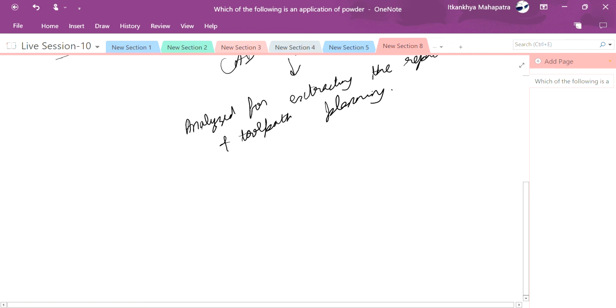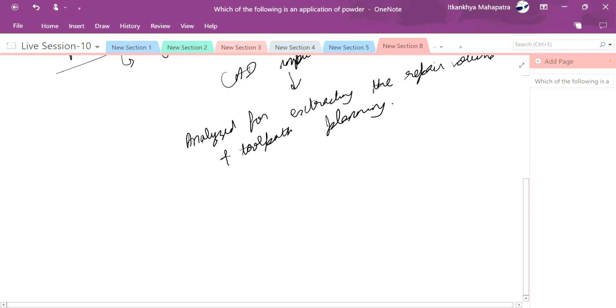The last one is grid stiffened structures. These are plates or shells layered with patterns of ribs in specific geometric configurations. They are usually used for high payload carrying capacity, so that we can reduce the structural weight.